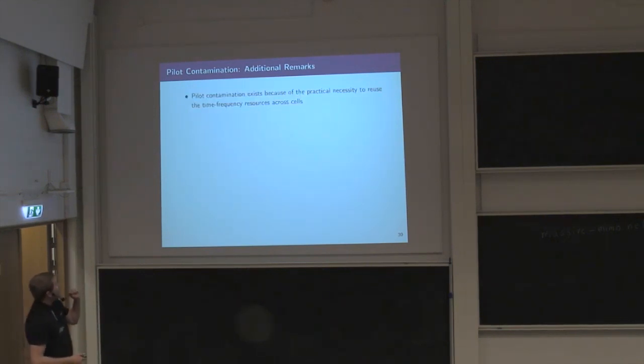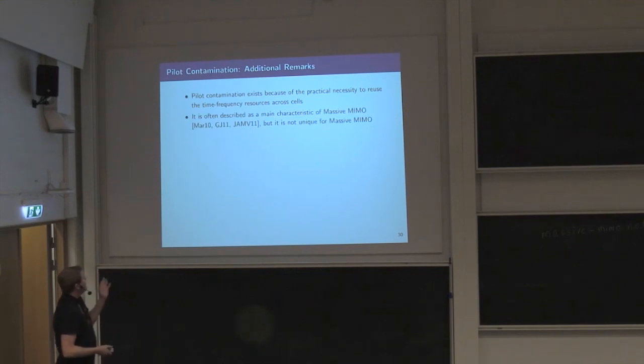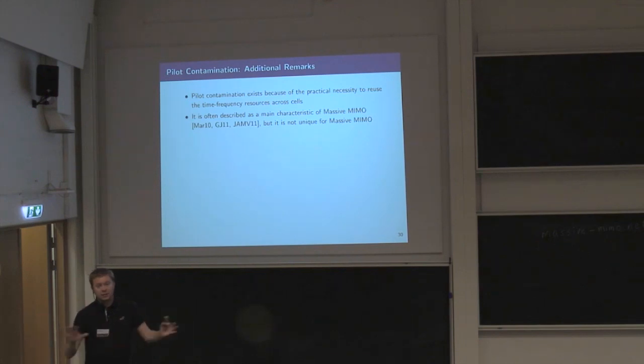So some additional remarks. Pilot contamination exists because of the practical necessity of reusing pilot sequences between cells. It's often described as one of the main characteristics of massive MIMO, but it's not unique to massive MIMO. This is something that you observe in any multi-user system where you need to reuse the same time frequency resources in different cells at the same time.